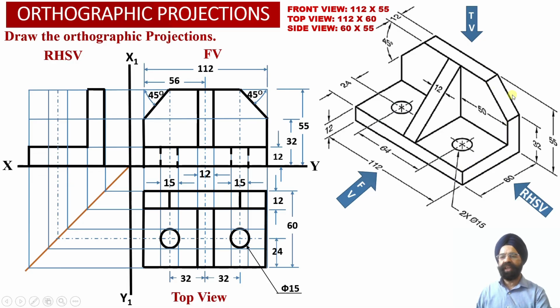we will check that this L shape projection is the projection corresponding to the horizontal element. This vertical projection corresponds to element number 2 over here. Now, into element number 2, we observe that this surface happens to be parallel to the profile plane, so it will be projected as true shape into the side view projections over here. Even this surface corresponding to element number 1 is also parallel to the profile plane, so this L-shaped surface has been projected as true shape projection into the profile view projection